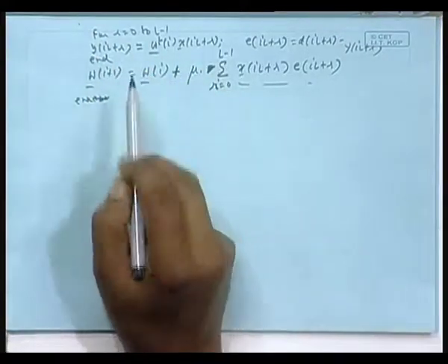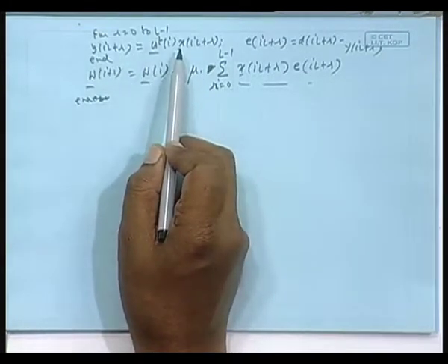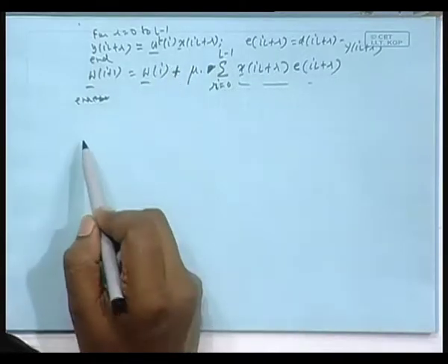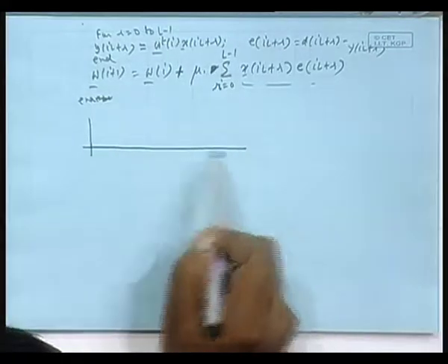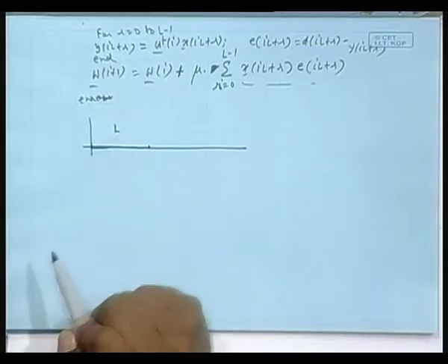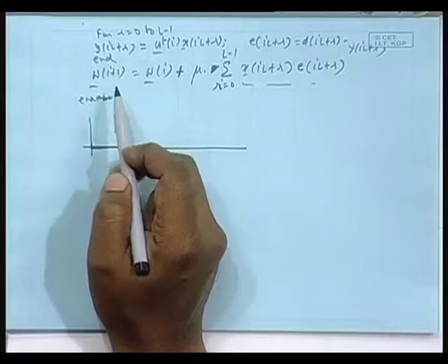Okay. Remember one thing, what we discussed yesterday, in the filtering part, we will follow overlap and save. In the overlap and save, what do we do? How will the blocks then be formed? That we have to discuss first. Suppose this is a block of length L, and what is the filter length? Filter length is capital N.